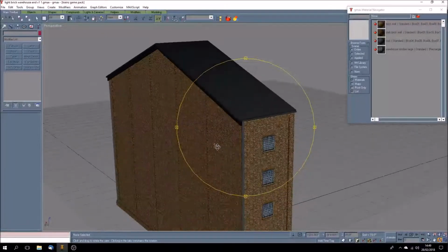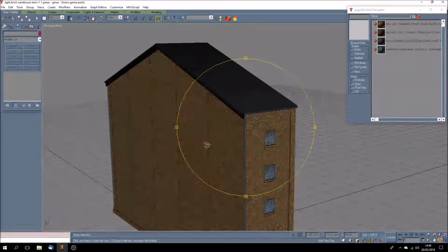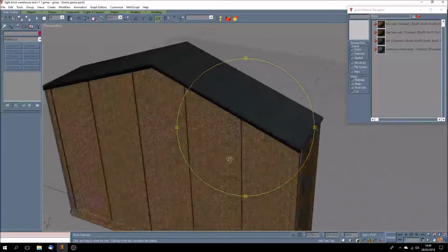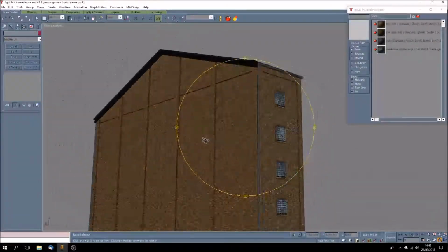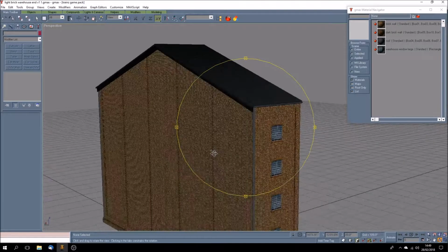Then my advice is to use a mix to create the background of the building, the main skin as it were of the building, either as a box or as a collection of two-dimensional editable splines which you then texture across, extrude and texture, and then delete the other faces that you don't need, and add in reduced meshes, that is meshes where you've tidied up the number of faces so you're not wasting polys, and you can be as simple or as complex, but the key with all this to make it look like something is to ensure that you have a collection of good textures to begin. Otherwise it will not look good no matter what you do.